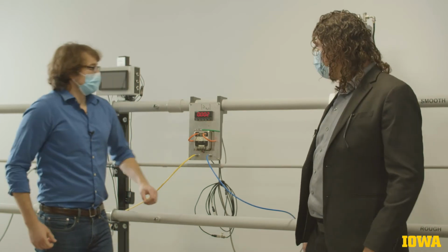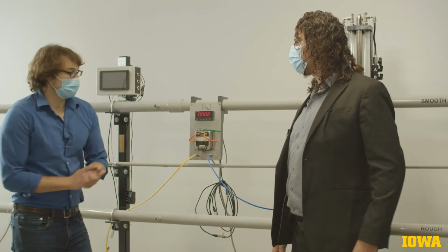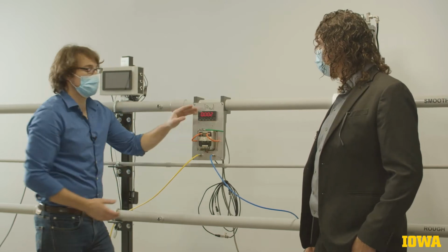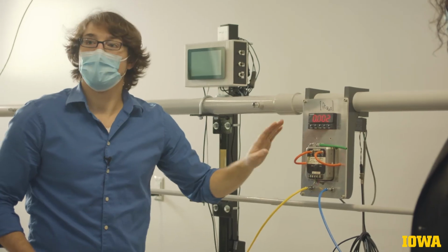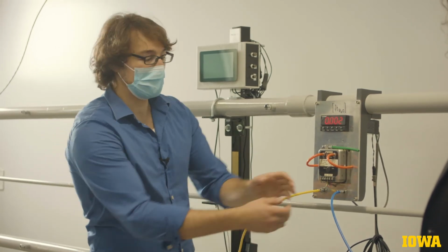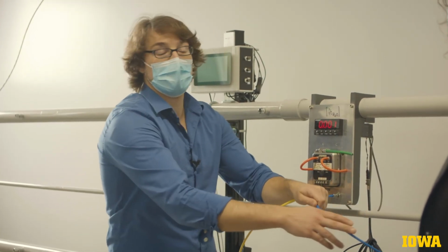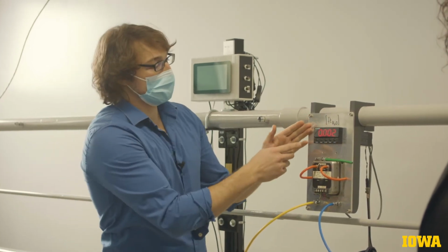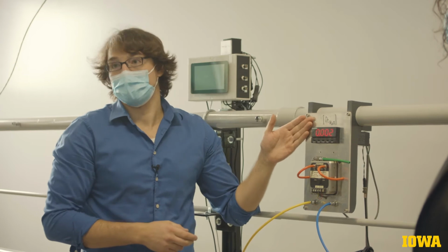We are now at the other end of the experimental setup, and we're going to describe the instrumentation we'll be using to make measurements. The principal piece of instrumentation we want to show you is the differential pressure transducer here, which is equipped with a digital display. A differential pressure transducer tells you the pressure on a high pressure leg relative to that on a low pressure leg. And the digital display, you may notice, is providing a reading in feet of water.